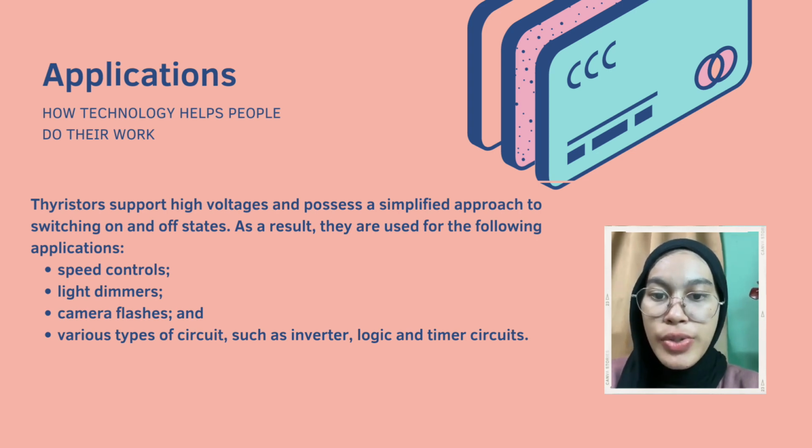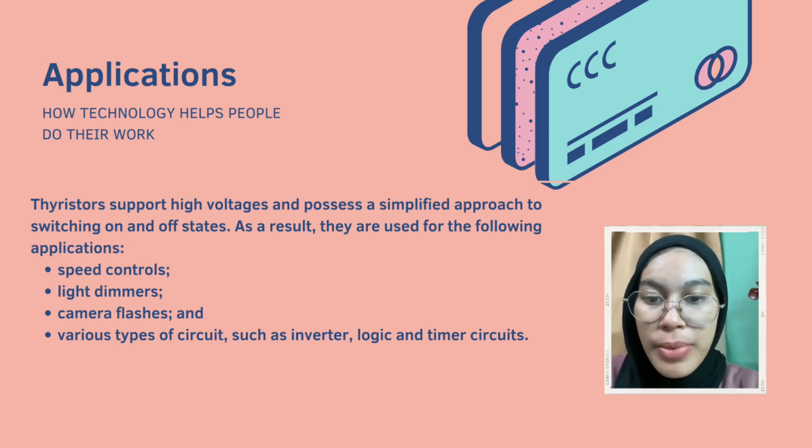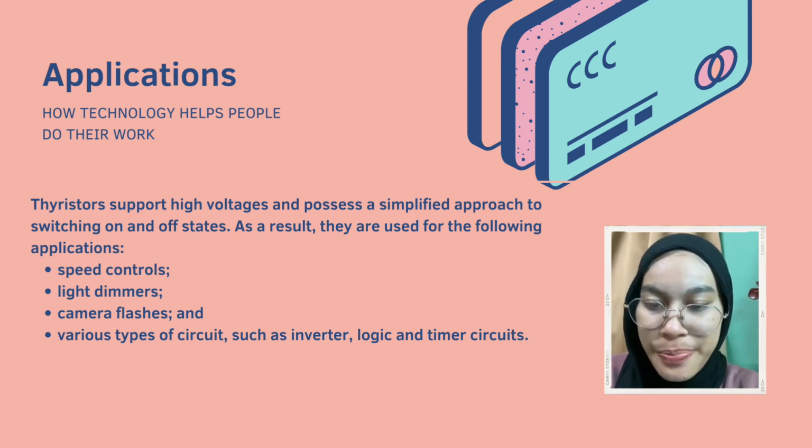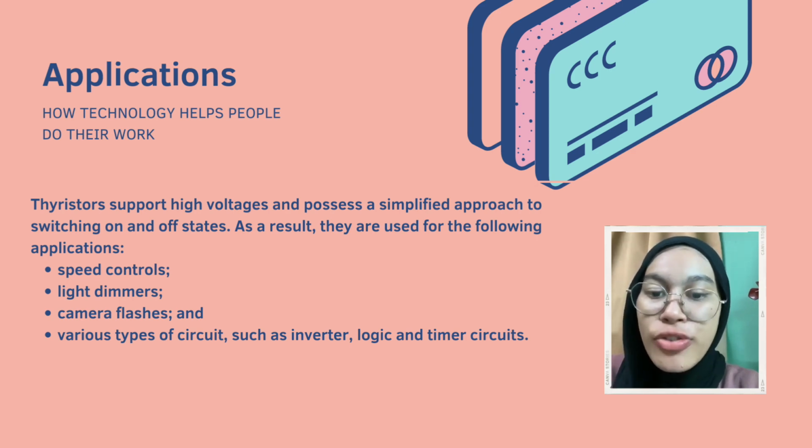Thyristors are mainly used where high currents and voltages are involved and are often used to control alternating currents, where the change of polarity of the current causes the device to switch off automatically, referred to as zero-cross operation. The device can be said to operate synchronously, being that once the device is triggered, it conducts current in phase with the voltage applied over its cathode to anode junction with no further gate modulation being required. The device is biased fully on.